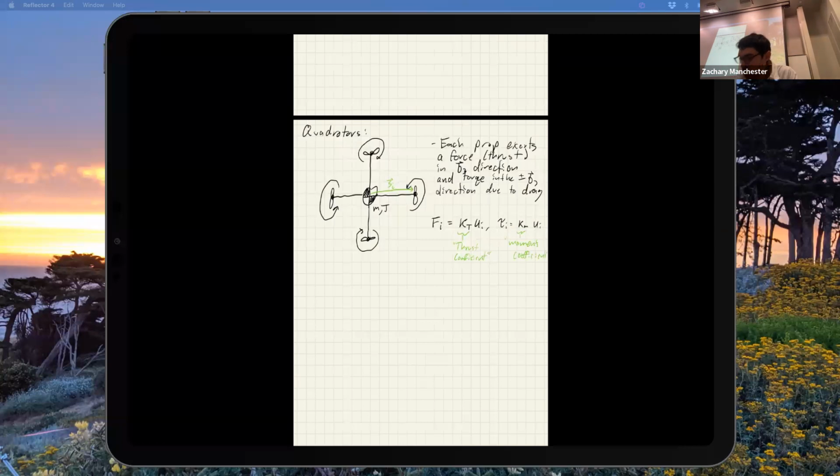And these are actually specs on the propeller. So for a given prop, you can either do wind tunnel experiments to figure this out, basically put it on a test stand with a load cell and free stream, measure this stuff and fit a line to it. Or for most anything above the crappiest hobby grade stuff, you can find these coefficients advertised for props. Anything above a certain price range, the manufacturer will tell you these.